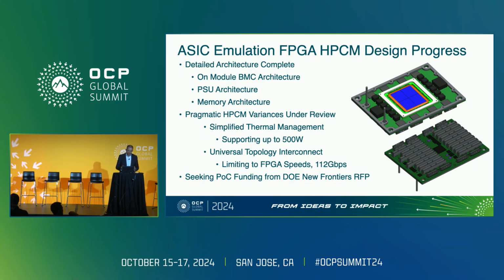We've got the memory architecture, basically 8 LPDDR4 packages, each package with 2 LPDDR4 channels in it to give us the 16 that we need. And all the power supply architecture is basically done. So the module is ready to go into its detailed design phase.